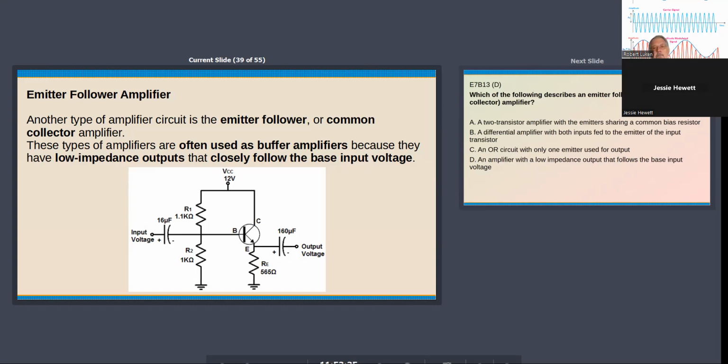That's all I can say about them, they're very common. What would be an application? Like I said, to isolate an oscillator circuit. In amateur radio, that would be used to isolate your VFO from your mixer, because the mixer is not going to be a high impedance, depending on the type of mixer. If you had that circuit in between, you could drive the diode mixer easily because it's going to be a low impedance.